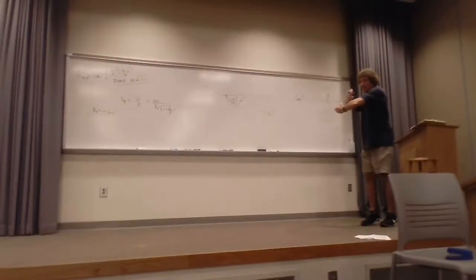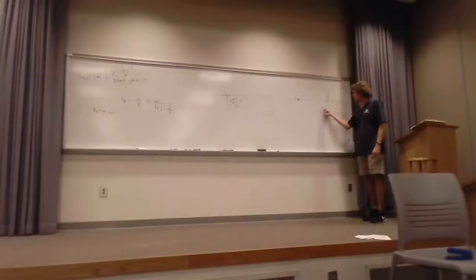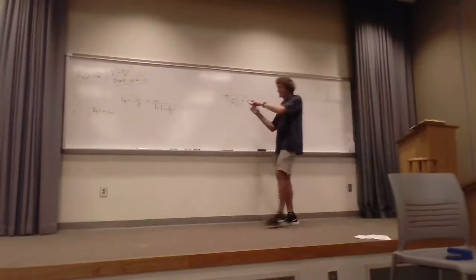But if you look at the intersection of the wave and the shoreline, as the wave's starting to make less and less of an angle, think of that as waves bouncing off the shore, then the velocity of the crest of the wave is much, much less than the velocity of that breaker moving, the actual wave action on the beach. Do y'all follow me on that? Well, if you're not, okay, I'll help you afterwards, but I want to finish this thought.